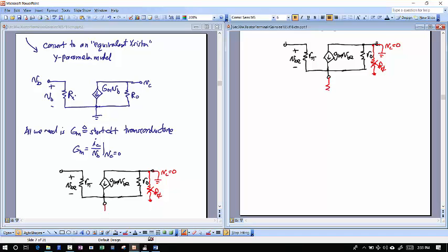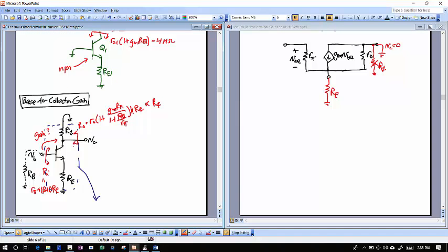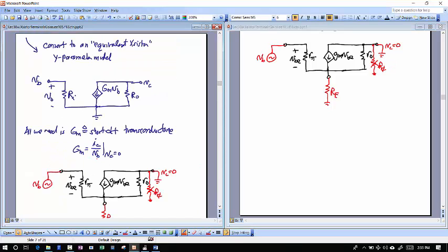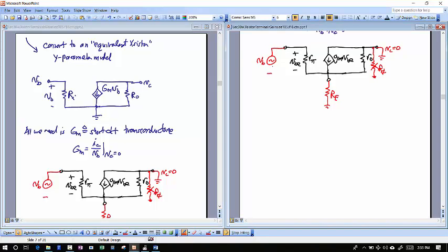My emitter has this emitter resistor, and I'm basically making the equivalent circuit for the original device that I'm analyzing, which is this one right here. Okay? And so the input here, I'm just going to drive with VB because I just want to satisfy the definition of this capital GM. I have to drive with VB, I have to measure the IC that results when the collector is shorted. Okay, so this is a circuit that I'm analyzing here. So let's go ahead and do this analysis.